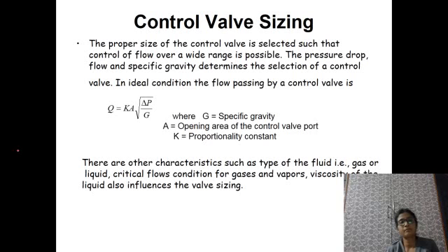So valve sizing means sizing of all the parts of the control valve. This is a very important aspect, and the proper size of the control valve is selected so that control of flow over a wide range is possible.